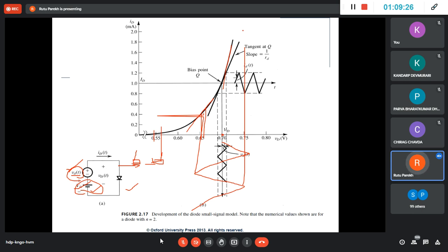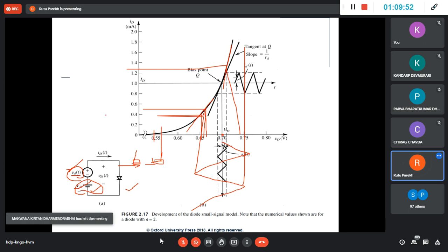This is the nature of the device, that for this voltage, every time I turn on the device, I will get this current only. If you turn it on and off 100 times at a particular voltage, you will get a particular current only. So if this range is large enough, your current is not going to follow the voltage and it will be non-linear, and then whatever you are processing does not correspond to your voltage.